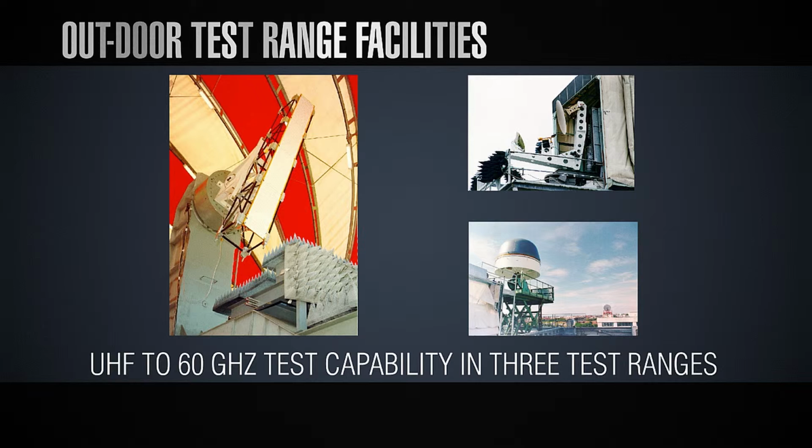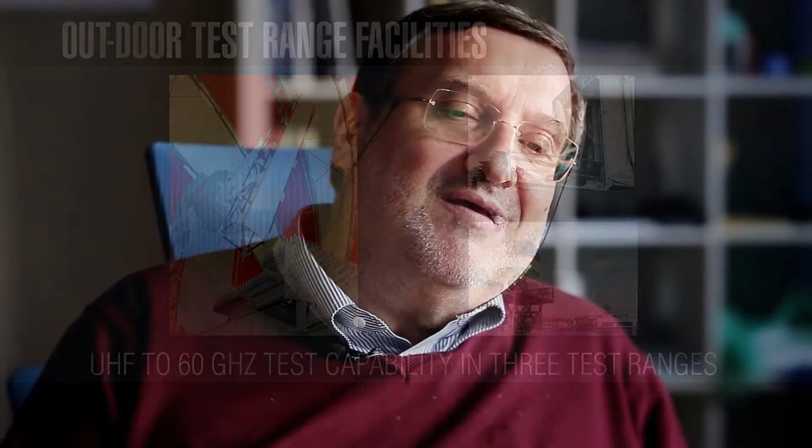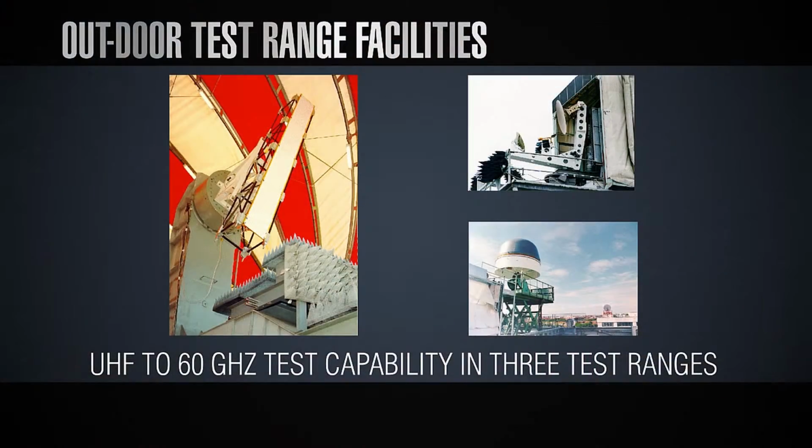We'll see that there are other techniques, but it's important anyway, depending on the choice of the approach, to know where the far field of the antenna is. And the far field starts, depending on the frequency of operation, through lambda and the size of the antenna. Very well. Having said that, as we said, we can test in far field, so we need to be far away from the antenna. Then we need what are called the outdoor test range facilities.